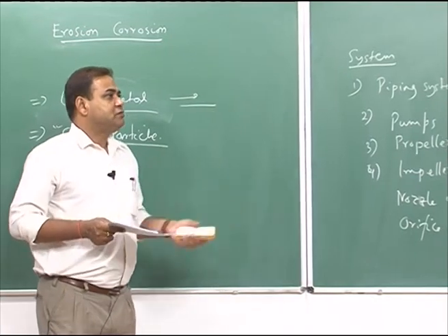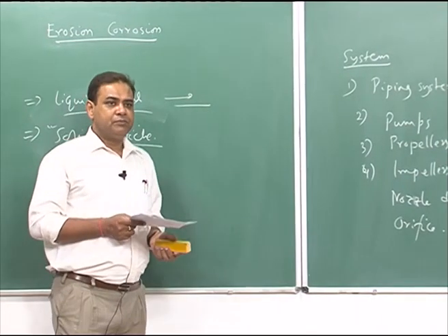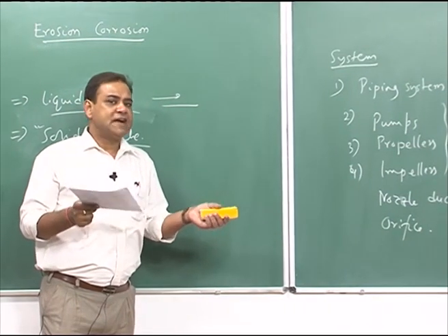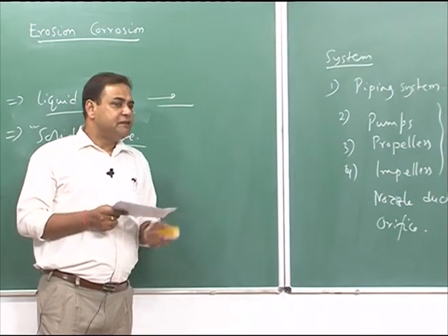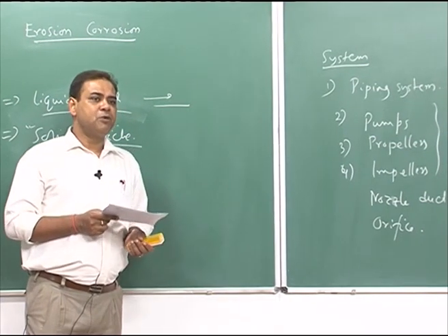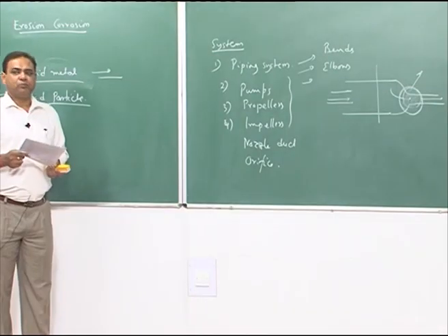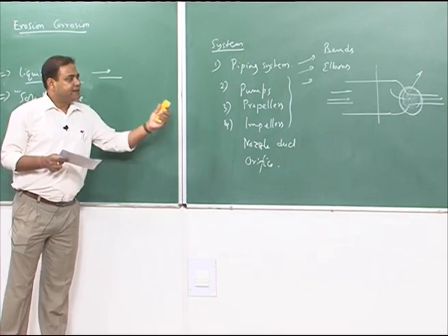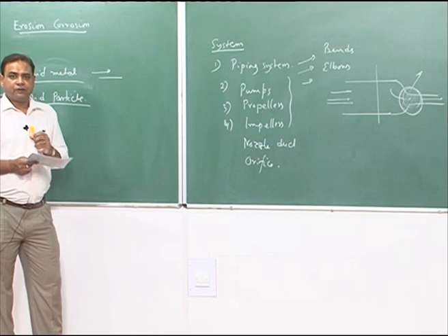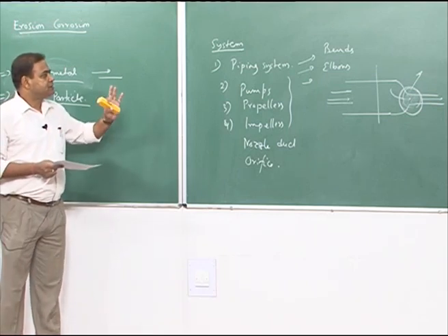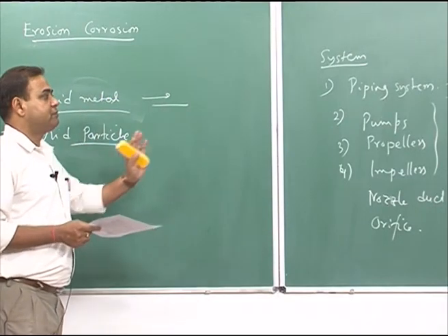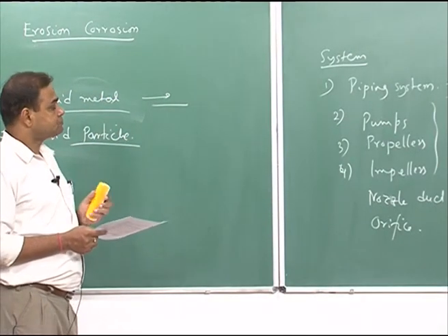Then the corrosion rate would be entirely different, because in the laboratory almost all the tests are done in static condition, and even if we have some movement, it would be very small. So, it will not depict the actual scenario. The laboratory test data cannot be considered for judging the erosion corrosion resistance of particular metals and alloys.